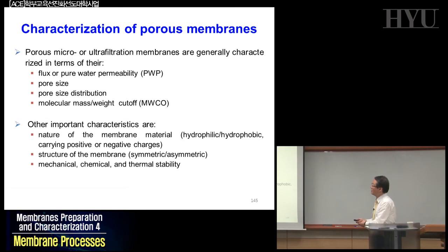In terms of porous membranes, such as for applications like ultrafiltration or microfiltration, we need to at least know about pure water permeability. When you cast a membrane, the first property that you have to see is the water permeability of pure water, not salt water, because salt water would only be applied to characterize RO membrane or NF membrane performance.